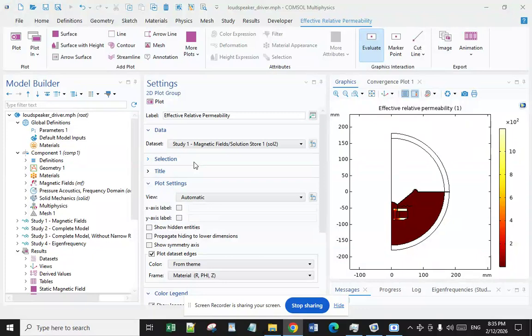And what are the advantages? Compared to piezoelectric transducers, electromagnetic acoustic transducer probes have the following advantages. The first advantage is that no couplant is needed, based on the transduction mechanism of electromagnetic acoustic transducers. Couplant is not required. This makes electromagnetic acoustic transducers ideal for inspections at temperatures below the freezing point and above the evaporation point of liquid couplants. It also makes it convenient for situations where couplant handling would be impractical.